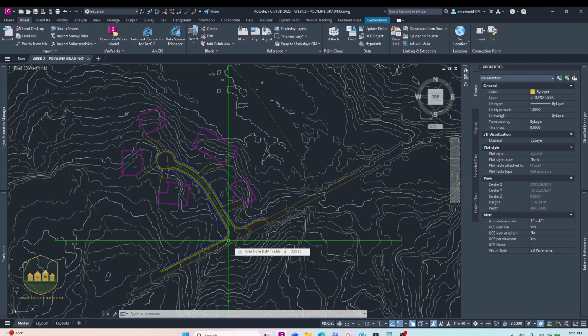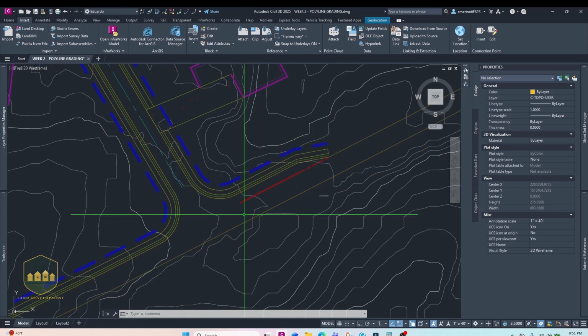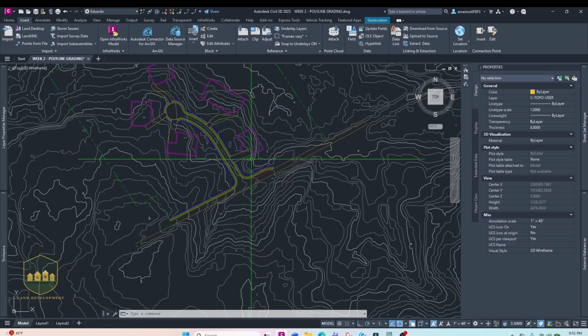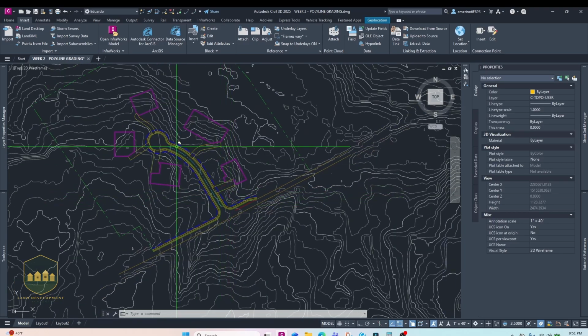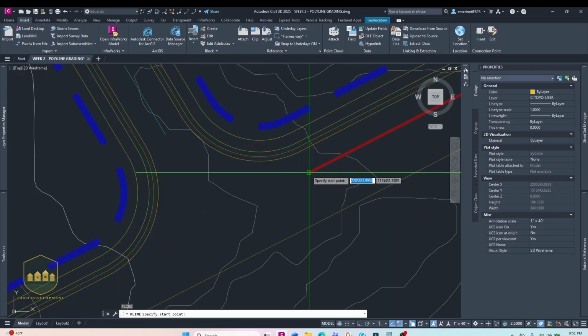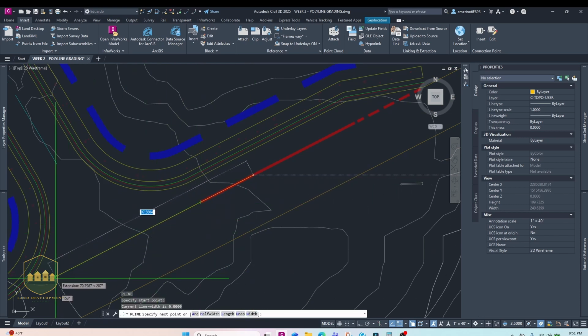So the biggest constraint is our existing road right here. We can't raise it, we can't lower it, we can't change it, we have to tie into it. So every time I start out grading a new development, I want to grade the main road and all the roads, but we just have one road for this development, as close as I can to the EG. Now I know my grading extent will be, here, let me just start here and do an extension.